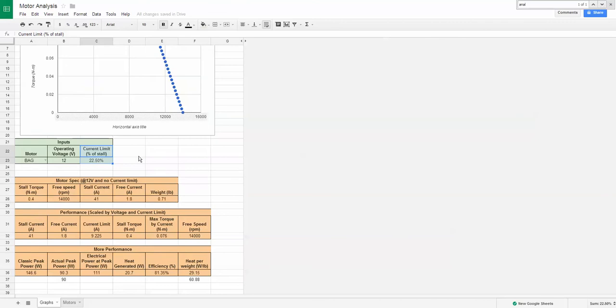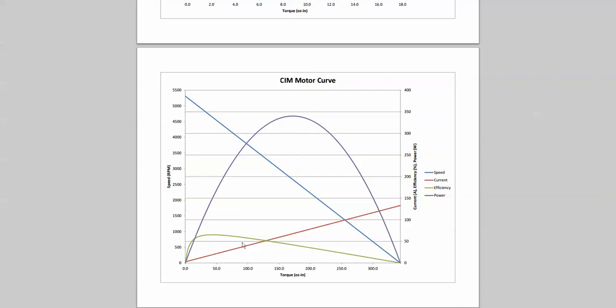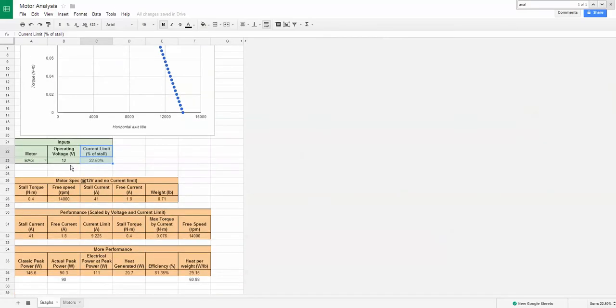So I hope everyone took away from this the rough concept of a motor and how torque and speed are trade-offs. And although if I didn't say it earlier, I'm going to sneak it in now. These graphs scale by voltage, roughly, or close enough for FRC purposes. So at 6 volts, everything would scale down by 1/2. At 3 volts, it would scale down by 1/4, and that's coming from voltage divided by voltage. So 3 divided by 12 is 1/4. And that is kind of shown here, but not great.